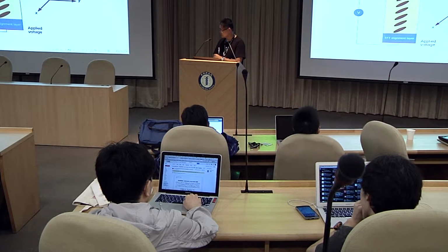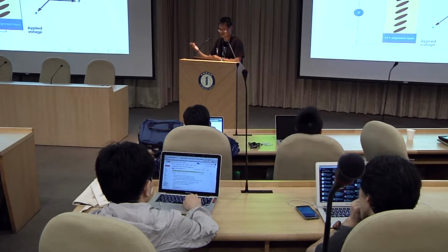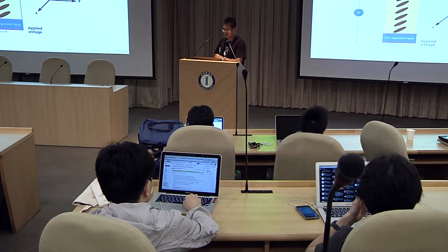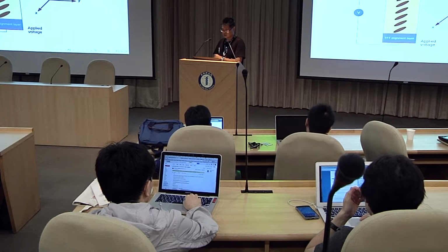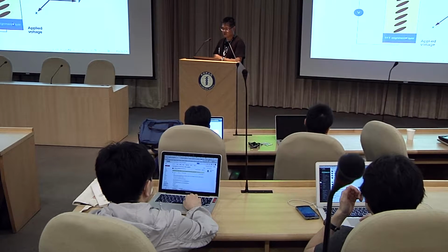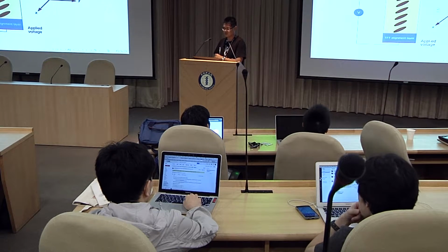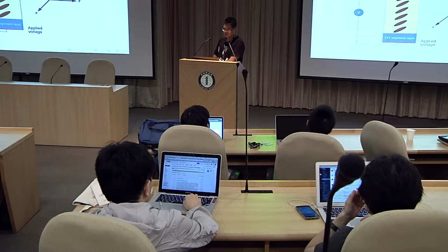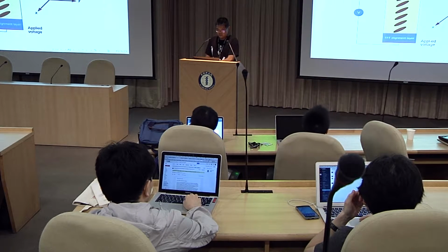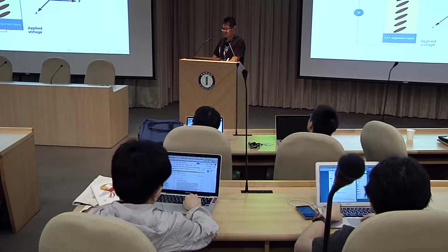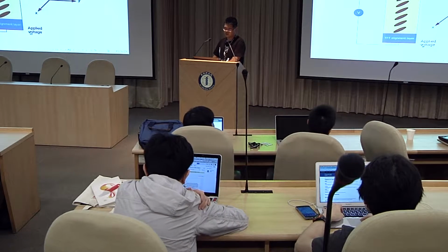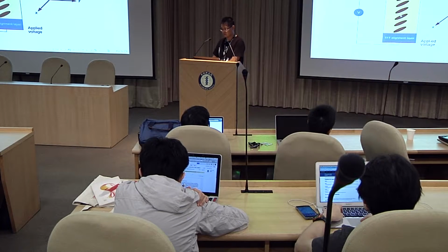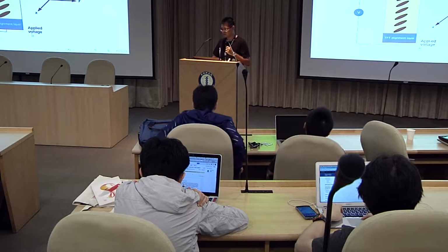The color filter that makes the pixel have color is on this side. So I call this the CF alignment layer, and this the TFT alignment layer, and the liquid crystal is sandwiched between them. And the coordinate system is like this. The light propagates along the z direction, and this side is always 0 volts. I set it as ground, and on this side is applied the voltage I want to apply on this liquid crystal cell.